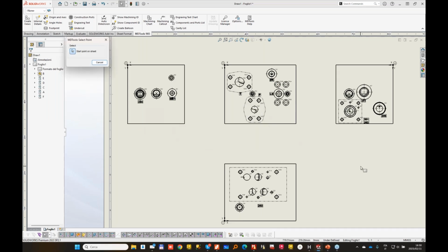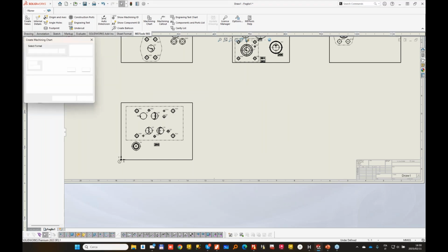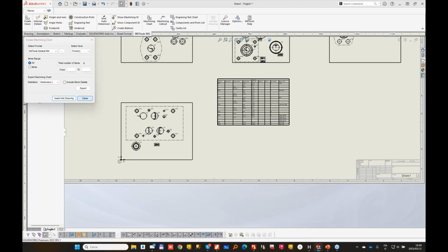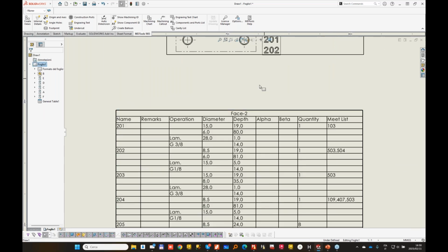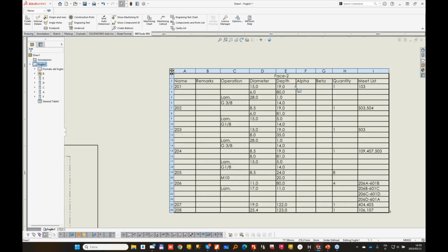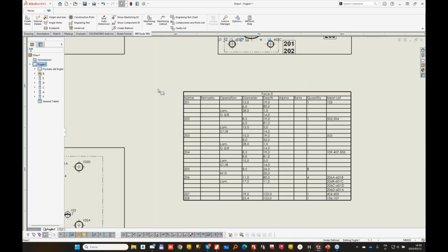So in my case, I've just created a drill chart for phase 2. With the older version of MDTools, it was possible to create a split chart by phase only through the automatic machining drawing. But later in the manual machining drawing, it was not possible. Now you have this flexibility, which I like a lot, because if you do drill chart drawings, then this will help a lot.